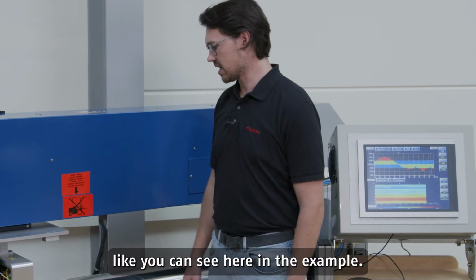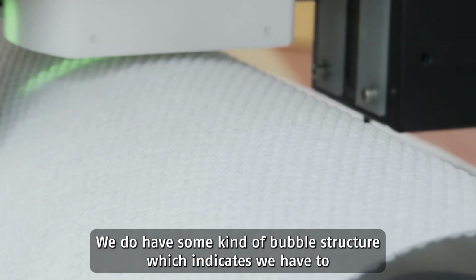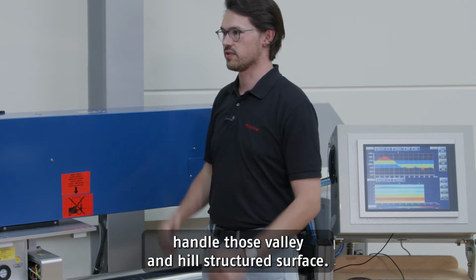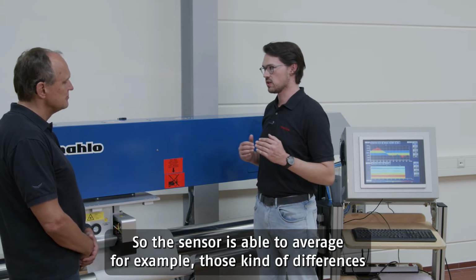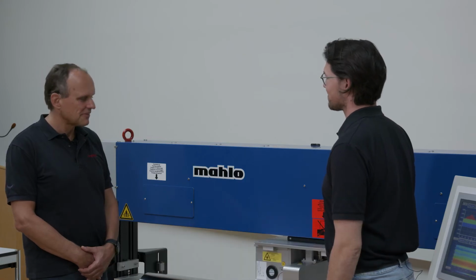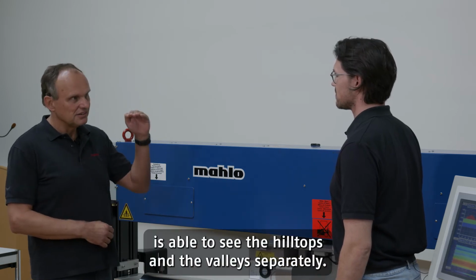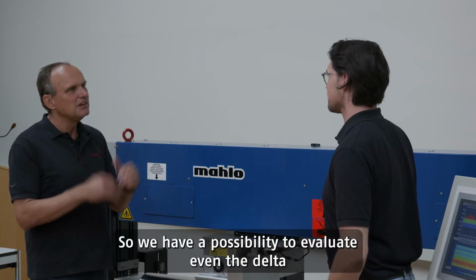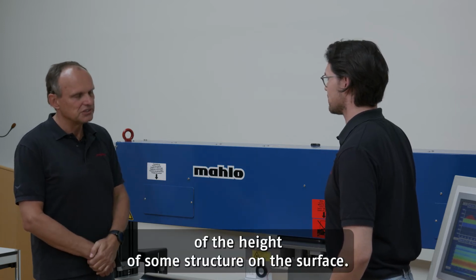Like we can see here in the example, we do have some kind of bubble structure which indicates we have to handle those valley and hill structured surface. So this sensor is able to average, for example, those kind of differences in the structure and also have some other advantages. And the line sensor is able to see the hilltops and the valleys separately. So we have the possibility to evaluate even the delta of the height of some structure on the web surface.